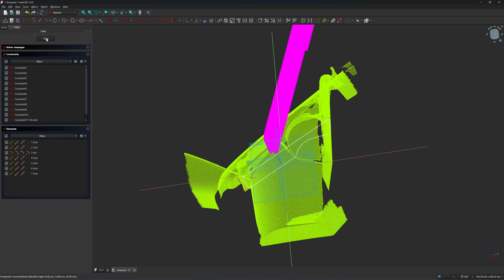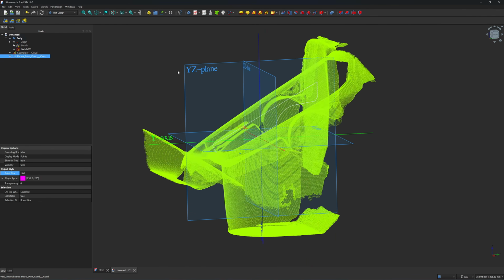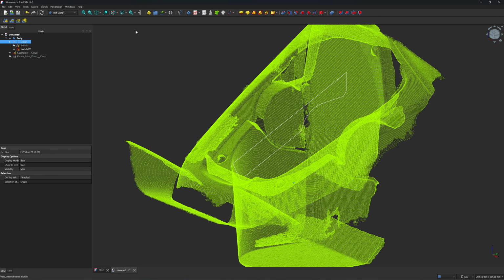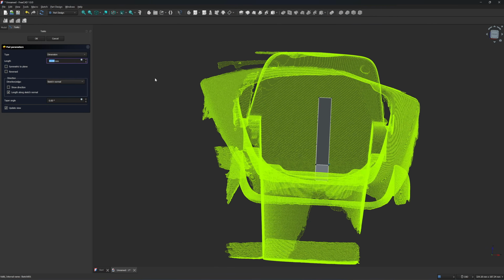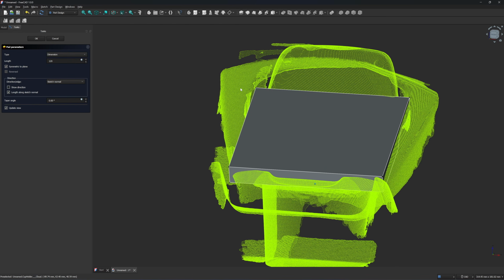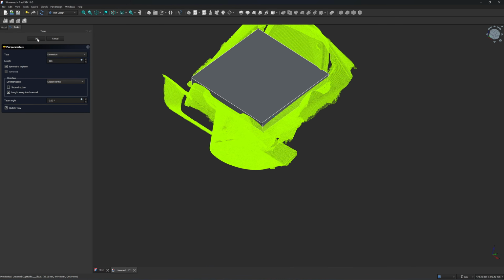Okay, I close it, and next I'm gonna turn off the phone first because it's dragging the performance of the software. I'm going to extrude it using the pad command. Click on the sketch first using a pad command. Alright, so I need to click on symmetry so that it will extrude on both sides. Let's try 120. So I'm going to make it a little bit bigger. Yeah, 120 would be enough. Okay, I click on OK.